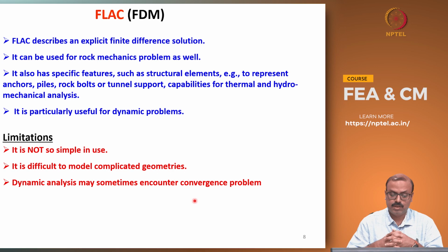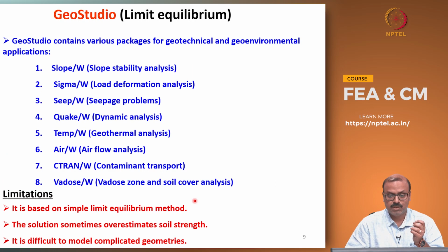However, the limitations are that it is not as simple as Plaxis. So, you need to know a bit more than what you are expected to know for Plaxis. It is extremely difficult to model complicated geometries, and dynamic analysis may sometimes encounter convergence problems.